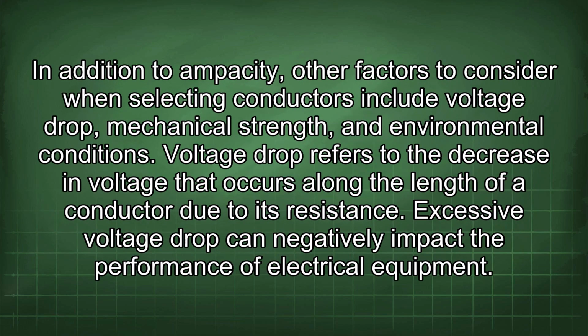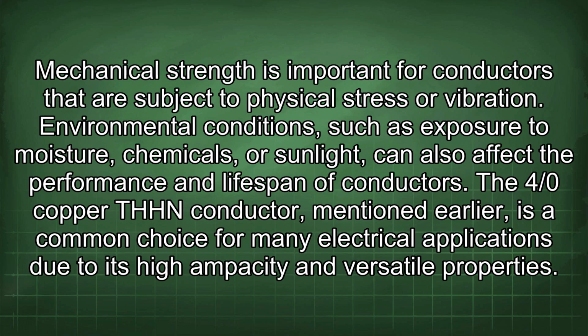In addition to ampacity, other factors to consider when selecting conductors include voltage drop, mechanical strength, and environmental conditions. Voltage drop refers to the decrease in voltage that occurs along the length of a conductor due to its resistance. Excessive voltage drop can negatively impact the performance of electrical equipment. Mechanical strength is important for conductors that are subject to physical stress or vibration. Environmental conditions such as exposure to moisture, chemicals, or sunlight can also affect the performance and lifespan of conductors.